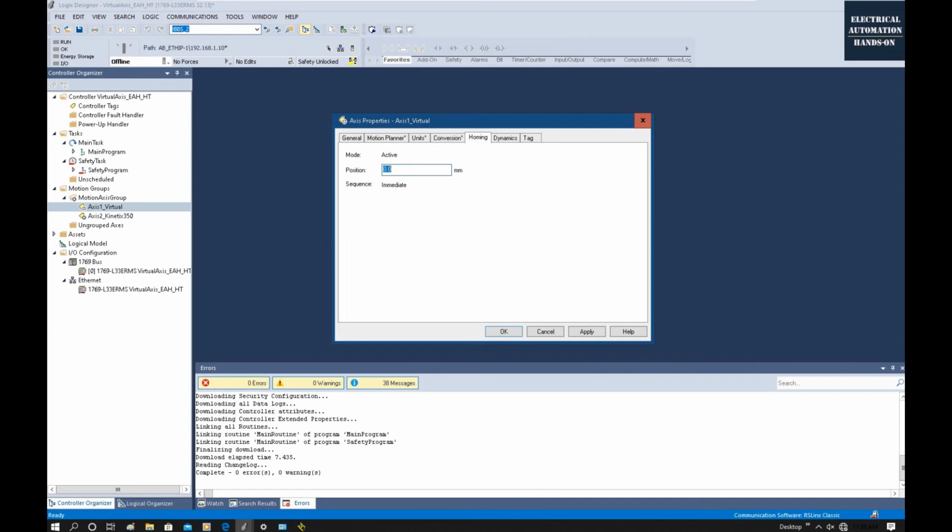So that position we will select as a home position. Therefore, if this is a perch position or this is the initial position, that value would be 800 or 1000. So this 800 or 1000 will be the home position value. Once we trigger set home, that value will directly be set to the axis, changing our axis position value.